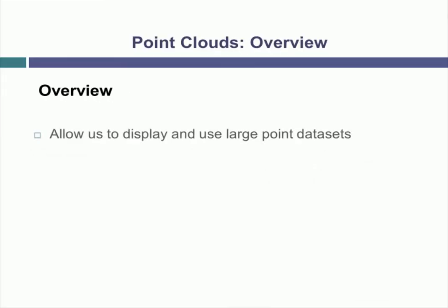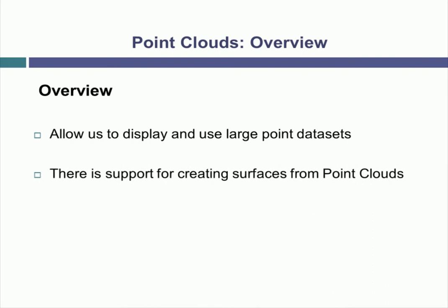Point clouds can be used in Civil 3D, and they allow us to display and use large point datasets. There's also support for creating surfaces from these point clouds, and those surfaces can then be used for typical things like volume calculations and as targets for grading or corridors.